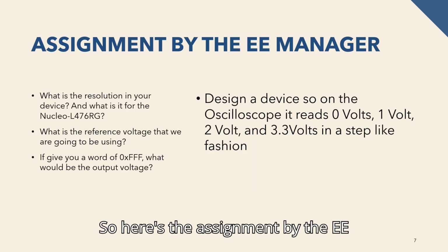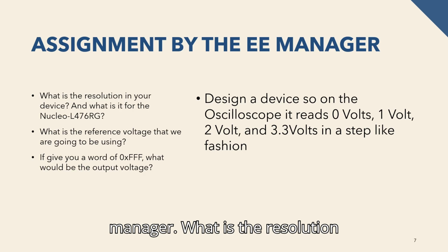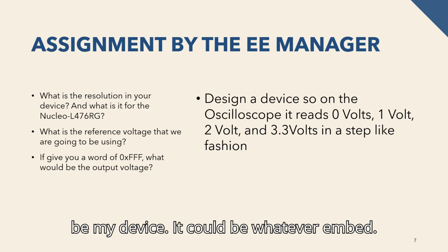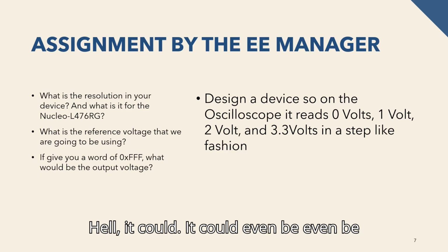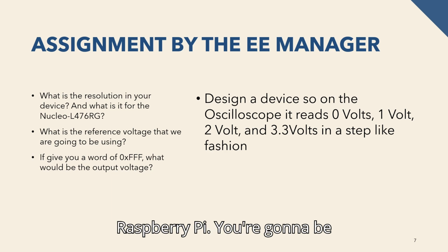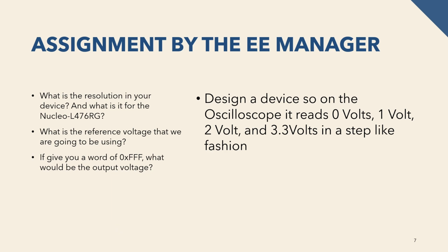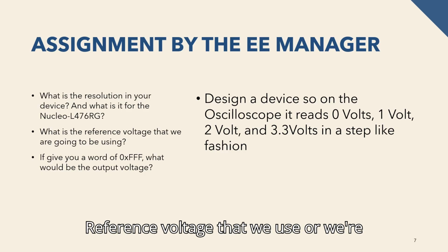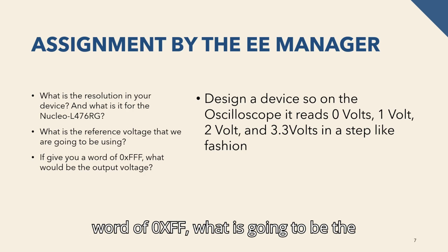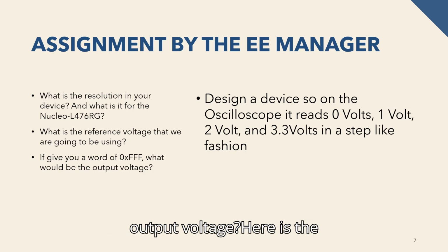So here's the assignment by the EE manager. What is the resolution in your device? It doesn't have to be my device. It could be whatever mbed, hell, it could even be Arduino. Maybe you can check the Raspberry Pi. You're going to be disappointed about the Raspberry Pi, though. What's the reference voltage that we're going to be using? And if I give you a word of 0xFF, what is going to be the output voltage?